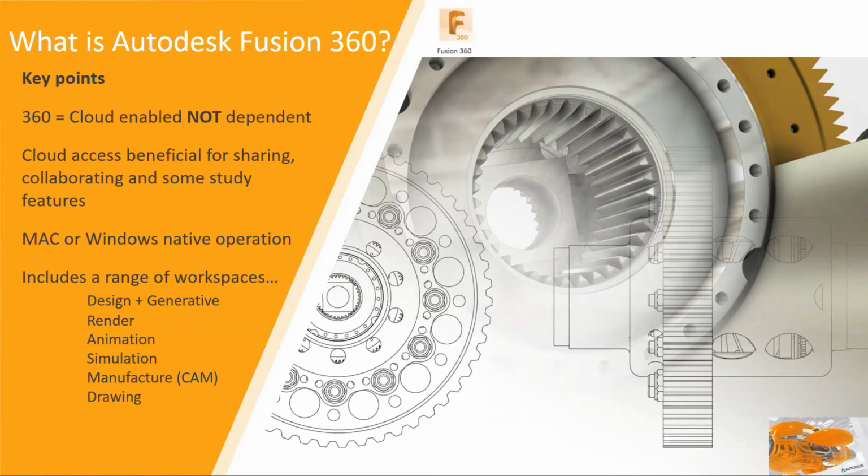Fusion also has the option to create sheet metal flat patterns. So we can create a flat pattern of a sheet metal model part. We can also animate exploded assemblies. And one of the other very powerful tools is the built-in CAM system, which Fusion leverages to allow us to output and post code to a CNC machine. So we'll be spending a little bit of time and focusing on some areas of those aspects during today's live demonstration, which will start in a moment.